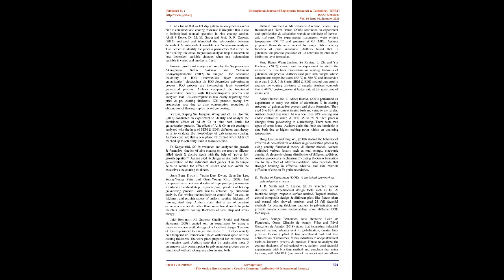D. Kopichinski, 2010, evaluated and analyzed the growth and formation kinetics of zinc coating on reactive silicon-killed steels and ductile steels with the help of a power law growth equation. The author used a Techni-Galva zinc bath for the galvanization of the individual steel grades. This technique helps to reduce the effect of silicon and also avoids excessive zinc coating thickness.